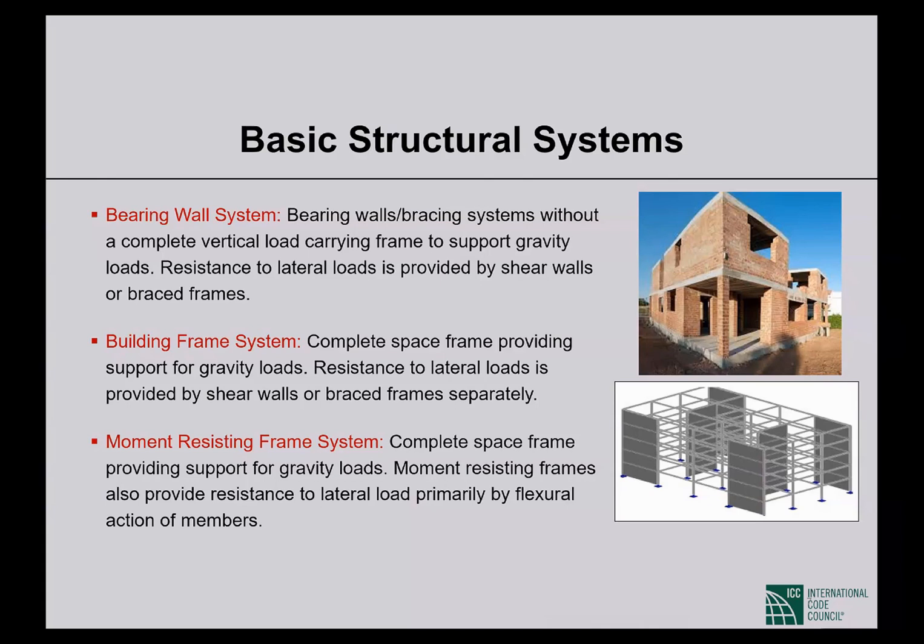That is like our old type brick buildings. The brick walls carry the gravity load and have a limited capacity to take lateral loads. In a bearing wall system, if it is properly designed, it is supposed to carry the lateral loads too. So I think you are familiar with that.